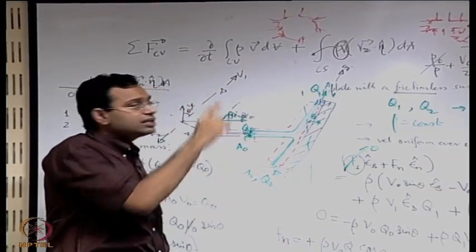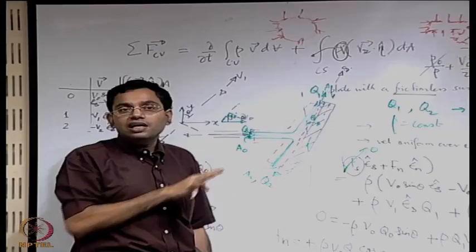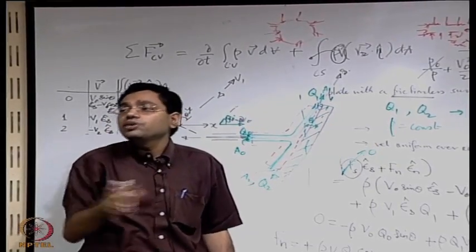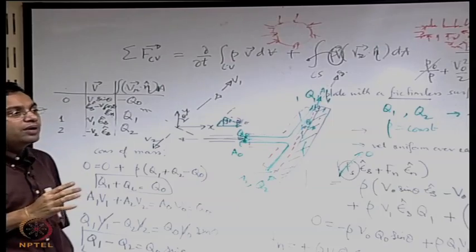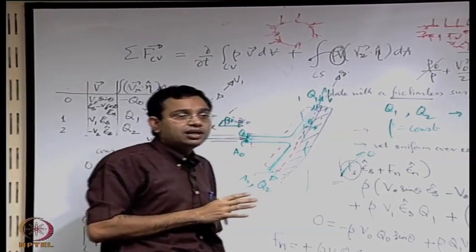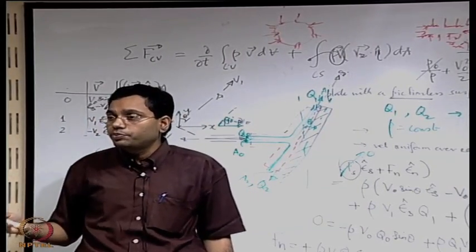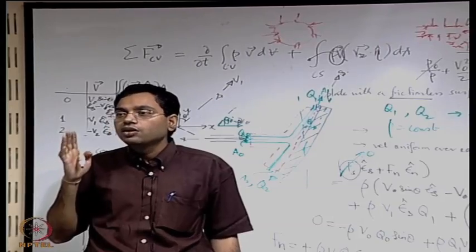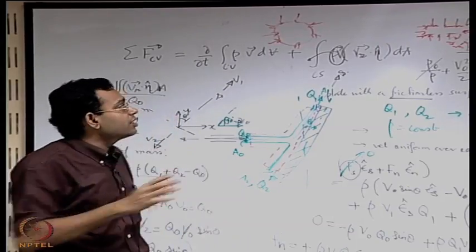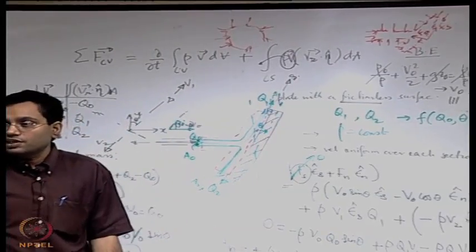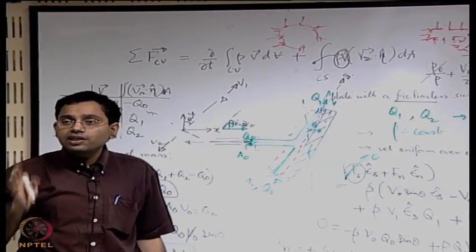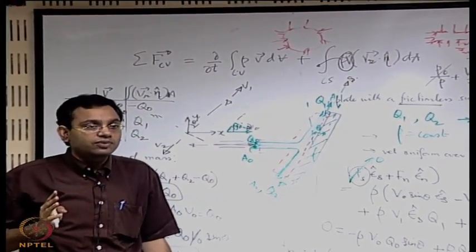Therefore our negligence of the pressure in this case has not mattered because it is a uniform pressure. That is why what is important for us is not the atmospheric pressure, but the deviation from the atmospheric pressure; that only can give rise to a local force. So always when we consider forces here due to pressure, we consider the gauge pressures at different sections, because the deviation from atmospheric pressure is what is interesting for us.